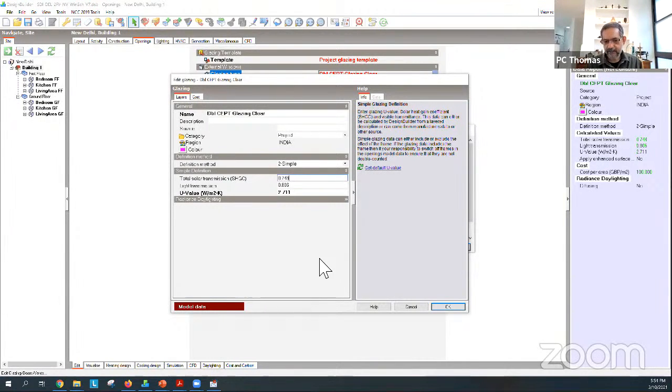Okay. Now U value is total thermal transmittance. So basically it says that if your transmittance is high, then for every degree temperature differential across the glass or the window, your heat transmittance is faster. So if you have a lower U value, then depending on the delta T across that, the heat transfer is slower. Okay. So in some situations, you want it to have a lower heat loss. In some situations, that may not be that important. I won't say that it doesn't matter, but it might be less important.